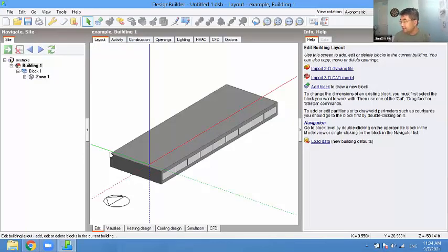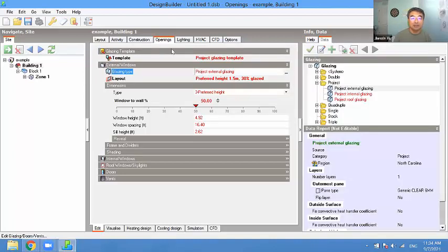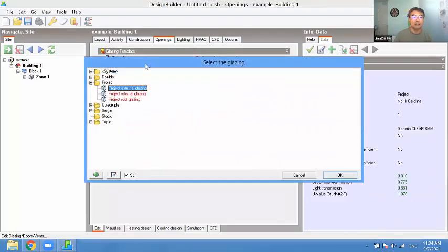Change the glazing type to double low E 6 millimeter and 13 millimeter with air. So we'll go to openings and then go to the glazing material, which is the glazing type, like here. You click on this glazing type, and then there are 3 dots showing up on the right-hand side here. Click on that. And then we'd like to specify the type of glass for this project.